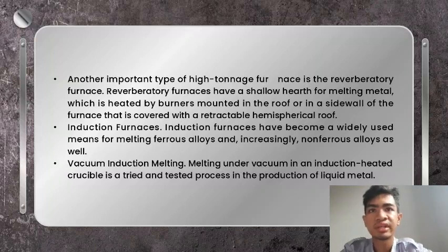Coupled with relatively low pollution and good thermal efficiency, induction furnaces are very efficient, are made in many different sizes, and are relatively simple in design and operation. Small quantities of materials can be melted rather quickly, which allows metal to be delivered at regular time intervals.